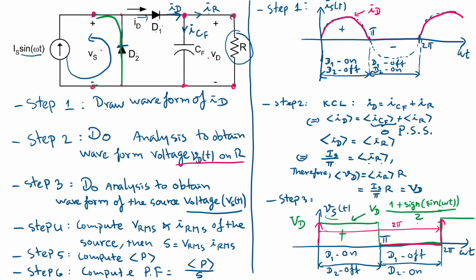And here there's no power factor due to displacement. In the inductive load from the previous example, the power factor is due to displacement. This capacitor is just to maintain the voltage at the load. It does not cause any reactive power.